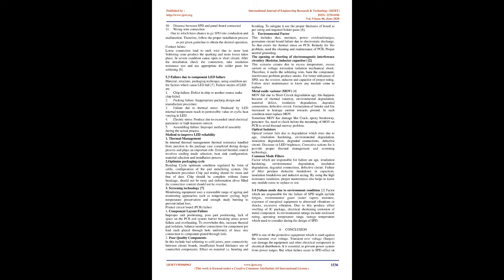2. Packing failure, inappropriate packing design and manufacture procedure. 3. Failure due to thermal stress, produced when LED internal temperature reaches the permissible value or by cyclic heat variation in the LED. 4. Electric stress, produced due to exceeded rated electrical parameters or high transient current. 5. Assembling failure, improper method of assembly during the actual process.